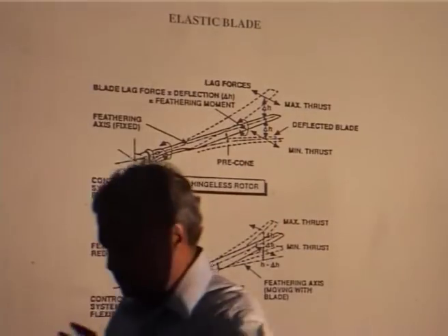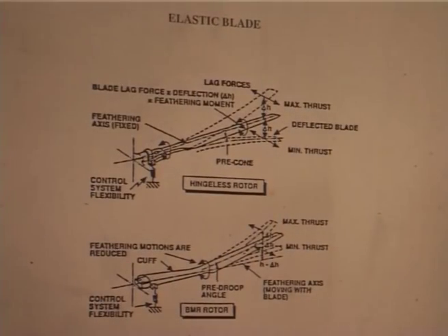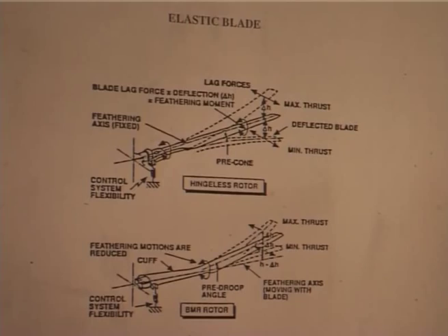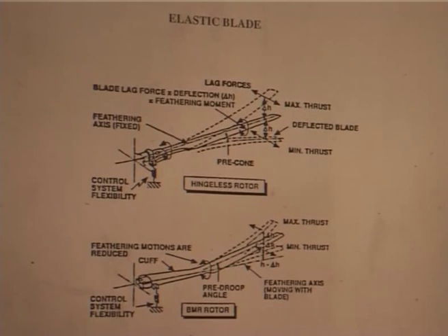So, if you do not take these things properly, your control rod loads, everything will be wrong. So, I will tell you, this is the structural part, the aerodynamic part is another. Usually predicting control rod load is always tougher. You really do not know, because of the elastic blade, now you take more modes into account, whether this is really happening, get all the moments properly and then transfer them.